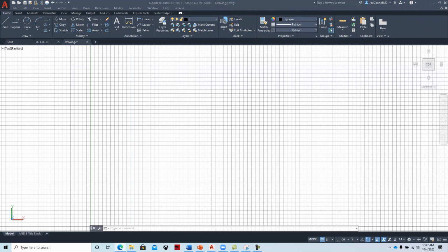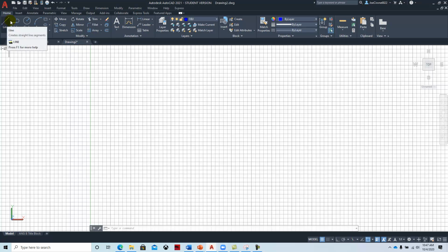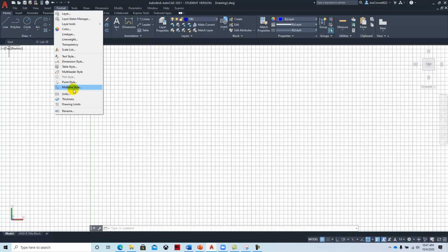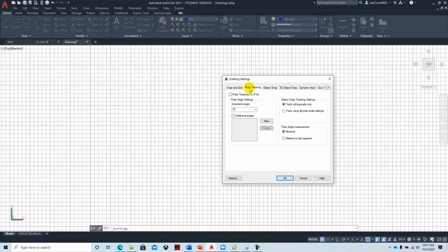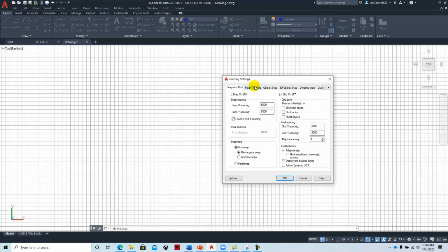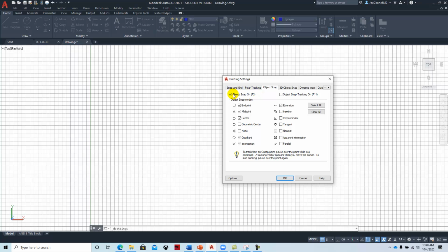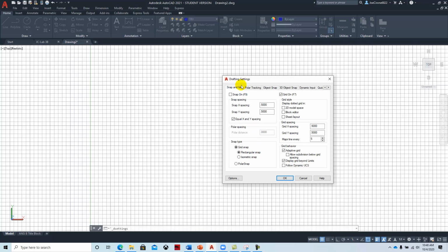So switching back to CAD, we're going to go to the object layer and start by drawing. Let's check our grid and our snap. I don't really think we need grid and snap at this point, so I'm going to leave it off, but I am going to make sure that my polar setting is on. I'm going to go to Tools, Drafting Settings, and Polar Tracking. I'm going to enable Polar Tracking and enable Object Snaps. I'll say OK. Let's turn off our grid.